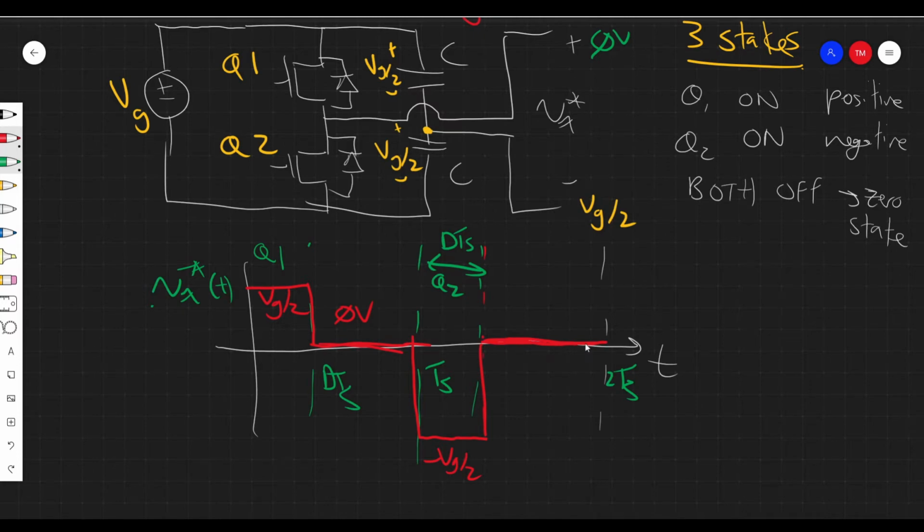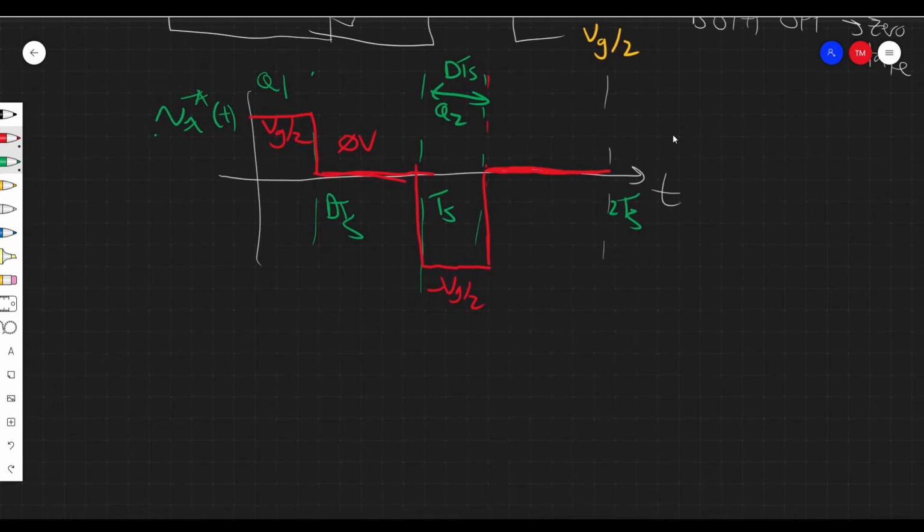So again, it's symmetric about the x-axis, meaning there is 0 DC component. And again, we can use this to send to a transformer and have an isolated converter, right? So we can use either one of these things. So this is like the first half. So this is one component we can use to construct a buck-derived isolated converter. Next, we want to look at the rectifiers.